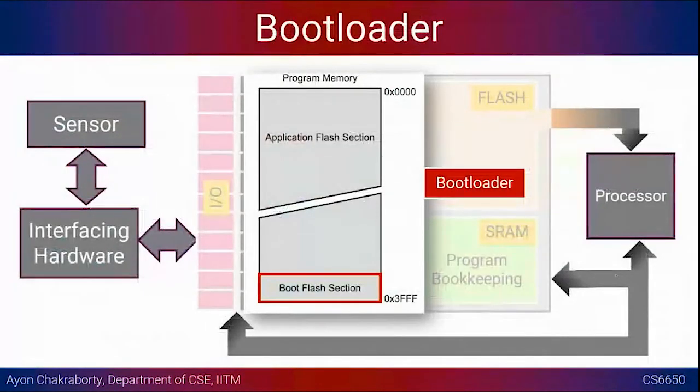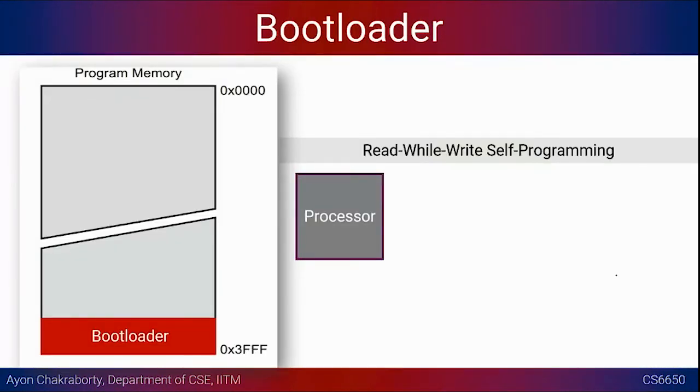So about the bootloader, I'm going to give you an introduction to what this is. Read this thing very carefully: read-while-write self-programming, it is called. It is going to read from somewhere. The bootloader is a piece of code. At the same time, it is going to write that to the flash memory, right? So it is residing in the flash memory itself.